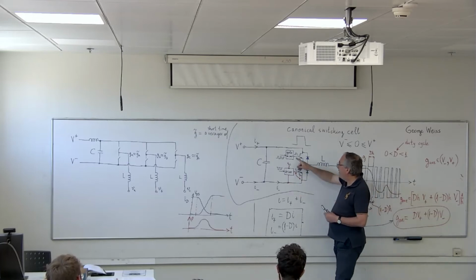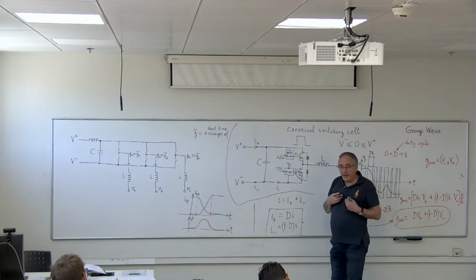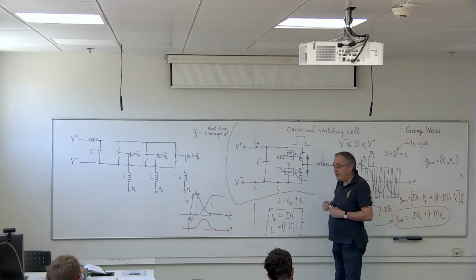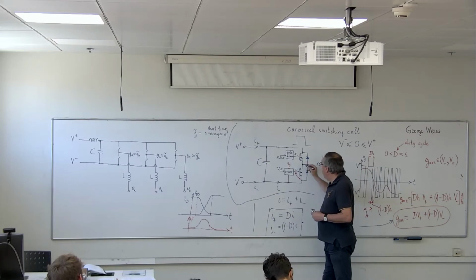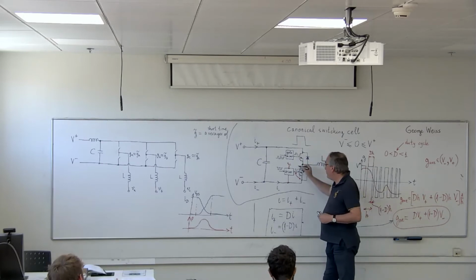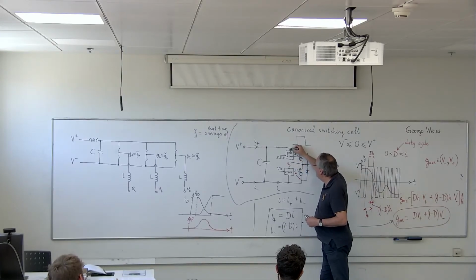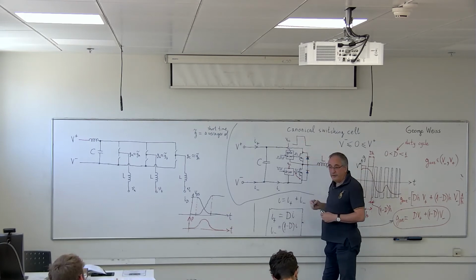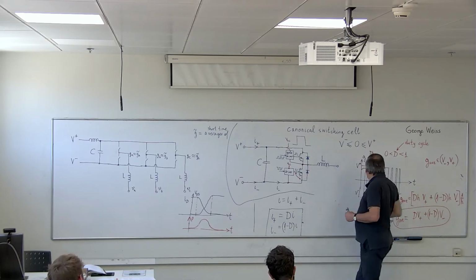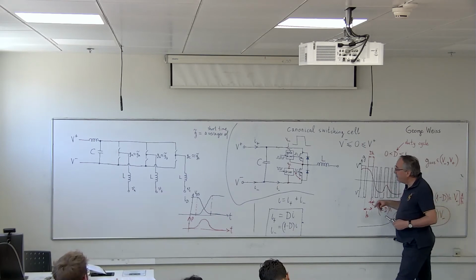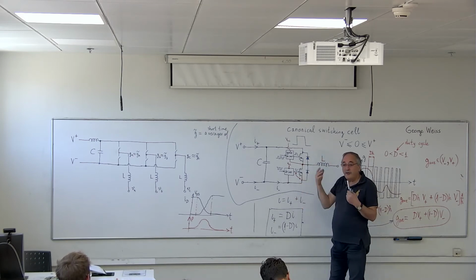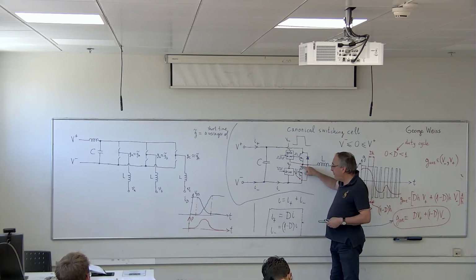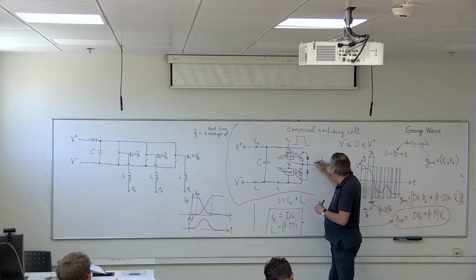And that will give you the corresponding output voltage with respect to this reference voltage on the gate. But what happens with the upper gate driver? Its reference is this point, the source of this transistor, the drain of this transistor. Then you need to generate this signal with respect to this reference point, which means you have to give it the power supply VCC with respect to this point. Now, this point is not constant. You remember, it's going up and down a lot. So you have to generate here a voltage supply with respect to a very, very non-constant, very fast changing reference voltage, which is this point, the point G. Remember, we call this point the point G.